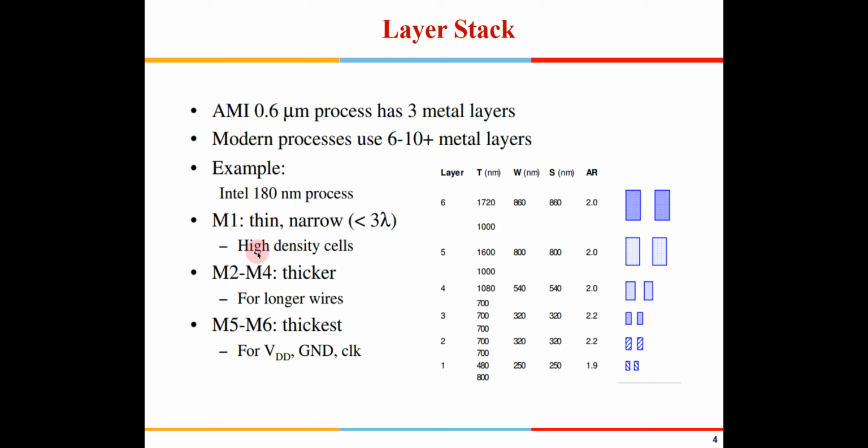First it will be the transistors, and then you have silicon dioxide, then you have a layer of poly. The poly forms the gate in many places. For 180 nanometer you generally have poly, but for 45 nanometer and other technologies, the gate is made up of metal, because we have scaled down the voltage to reduce the threshold voltage. So we have changed the gate from poly to metals like molybdenum and tungsten. These are the gate metals being used these days.